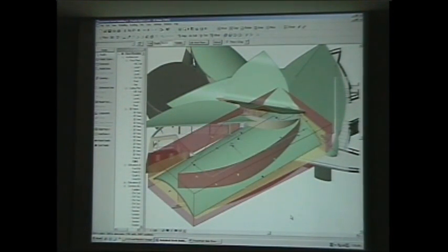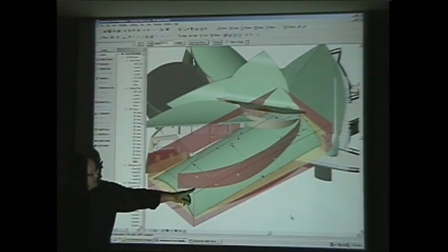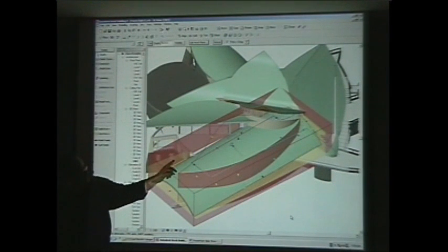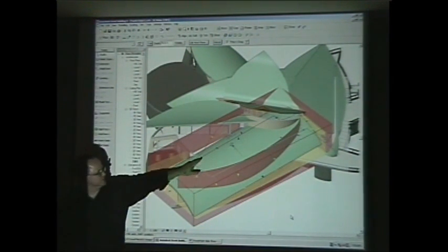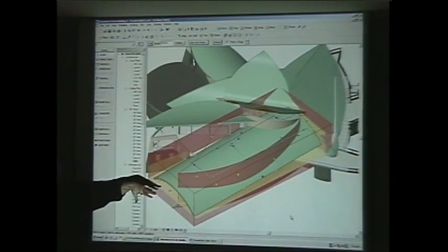The green form is just a roof by extrusion, this shape here, running back to the building. It's then broken from the work plane on which it was created and tilted, and then simply a void shape, like a donut, so that it's removing the outside, is used to leave us with this sort of leaf form roof.